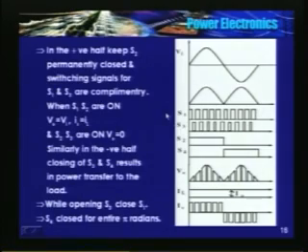How does the output voltage look like? Whenever S1 and S2 are on in the positive half, output voltage is same as input voltage. So when S1 is opened and S2, S3 are on, load voltage is 0, freewheeling period. Waveform is very simple. When S1, S2 are on in the positive half, input voltage is same as the output voltage, and when S1 is off, S2, S3 on, load voltage is 0.